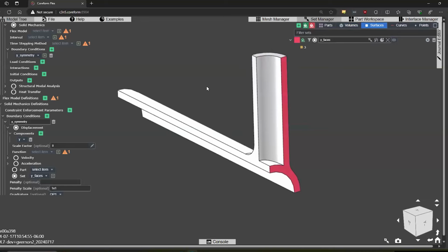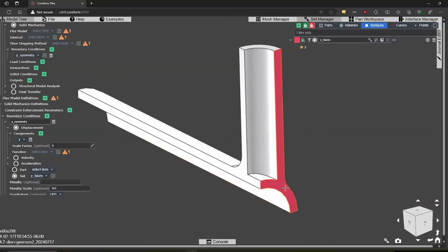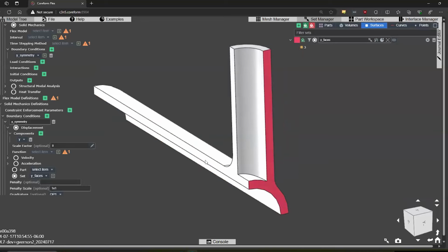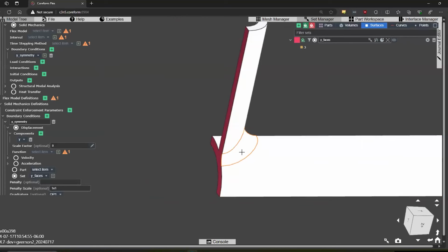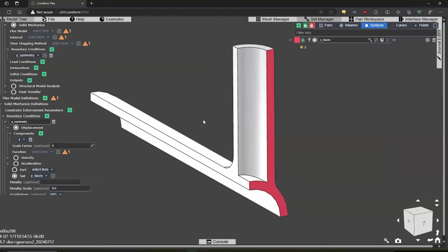But notice that I've assigned this boundary condition directly on my CAD geometry without even having to think about meshability. So, this fillet on this backside, if I wanted to build a body fit mesh in the traditional manner, I'd have to do quite a bit of decomposition of my geometry or just removing that fillet altogether. But I can really leave meshing as an afterthought in my workflow. And I think that's a really important key distinction to make. So that is now fully defined, that boundary condition.